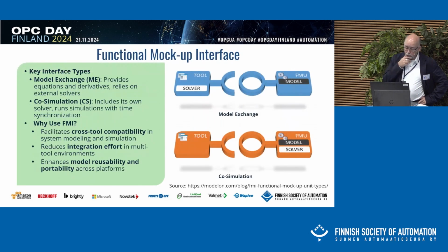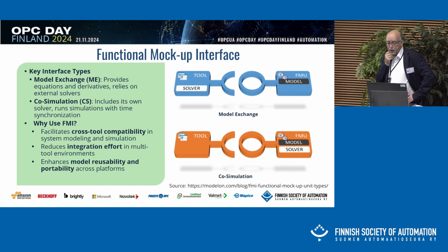And so what we go through is there are different types of these simulation models, model exchange and co-simulation. So we can run both. In model exchange, the FMU contains just the model and the tool contains the solver part. In co-simulation, you have the solver also inside the FMU. And there is the time synchronization, and now version 3 is coming, with which you can also run scheduled execution. Not all the tools are yet providing that version 3 scheduled execution, so we were using version 2 of the FMI.